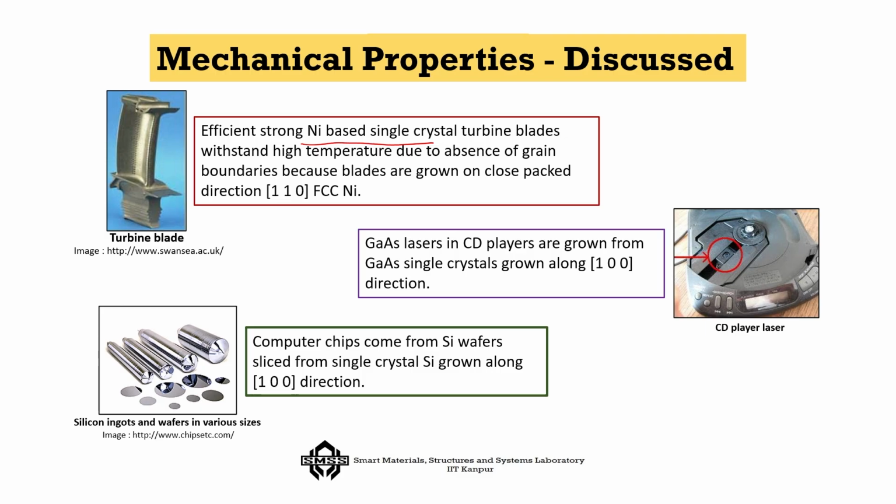If there are polycrystals, there will be grain boundaries. Also, they have different directions of close packing, and that will influence the decision, such as for the FCC structure of nickel, which has a close packing direction of 110. So, that is the Miller index contribution to the choice of the material. I will come to it towards the end.